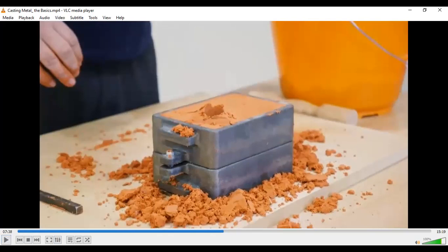Right, that taper is given intentionally so that we can remove it easily, as he was explaining with that cylinder. If it is straight, then when you are removing it, that will cause a disturbance and the sand may come off. So that taper is provided. Generally, if you observe many products, you have a taper. That is one of the reasons why the taper is given, for the ease of removal of the casting.